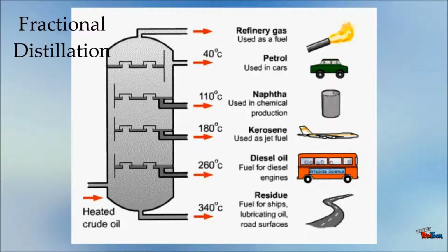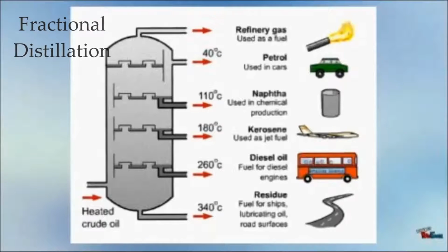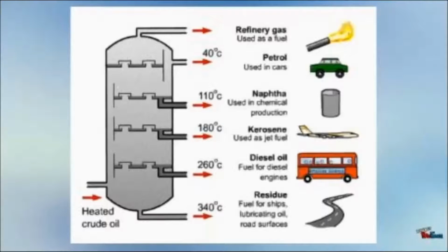Fractional distillation of crude oil uses boiling points to separate the different parts of the crude oil. The crude oil is heated to about 350 degrees Celsius. The vapor of the oil cools to about 75 to 190 degrees Celsius and condenses to produce naphtha. Naphtha makes up about 20 to 40% of crude oil, with 6 to 10 carbon atoms in its molecule fraction.